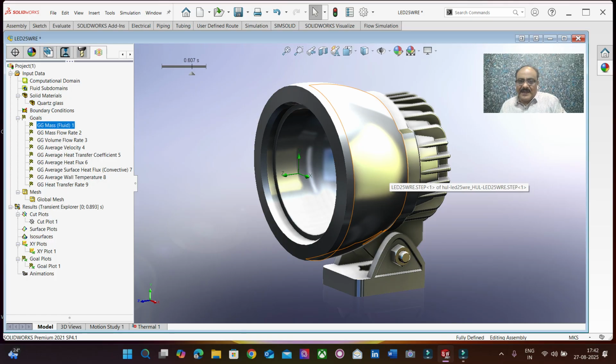Now, because of that temperature, is there any material which is going to radiate off, or whether it's going to flow off? Instead of using aluminum alloy, if I try to use a metal or an alloy which is very low in modulus of elasticity, say the Young's modulus is very low, then because of this particular temperature, which is 1900 Kelvin, there is a probability that the metal or the alloy can flow. If it flows, then there is certainly going to be a change in mass. That means there is going to be heat and mass transfer simultaneously.